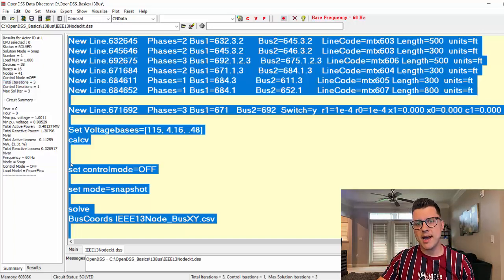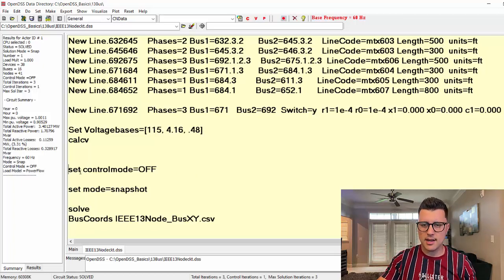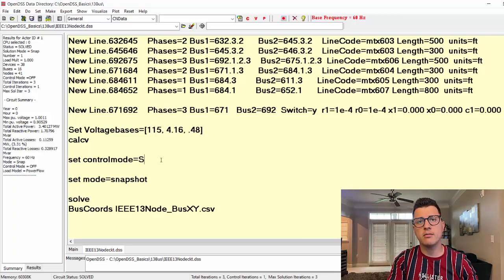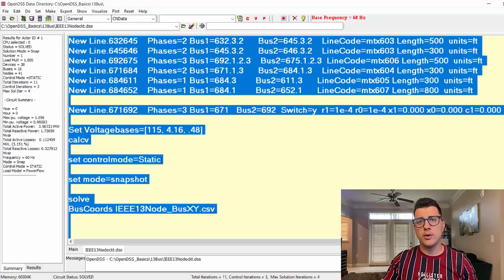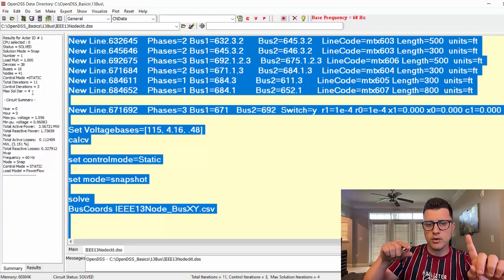So if I come back here, take this off, okay, and run OpenDSS again. I know OpenDSS uses static as default, but we are learning here. We run that, and you see 11.4. So I just saw that when you perform just the power flow, the first power flow, this is the same as when we are doing here the first control iteration.